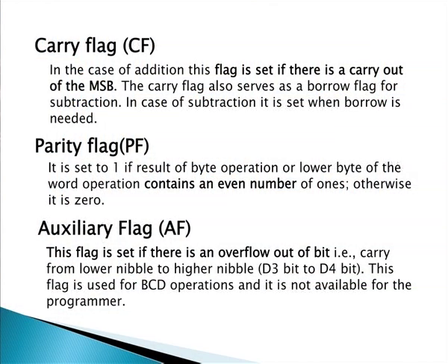Actually, a flag is nothing but an SR flip flop which is set or reset according to the result of the arithmetic or logical operation performed by the ALU in the microprocessor. Now, we will discuss the flags one by one for their set condition and for their reset condition. Let us start with the carry flag.